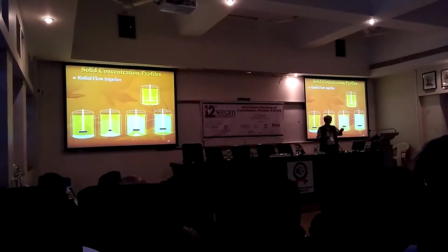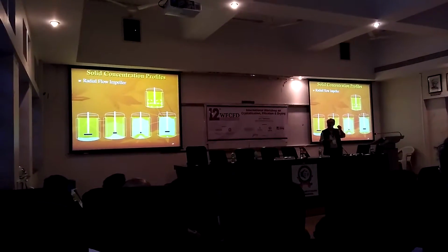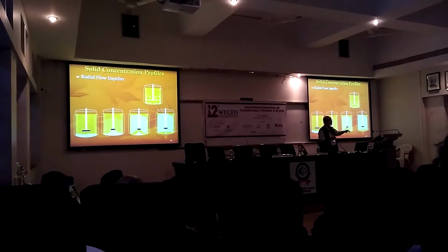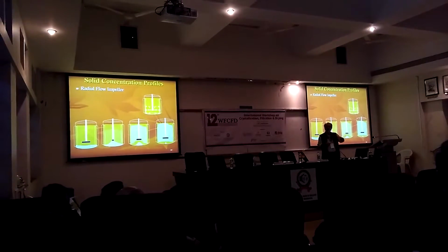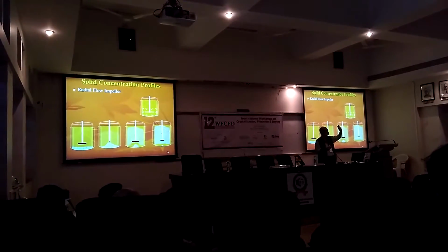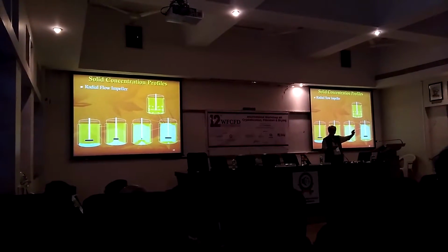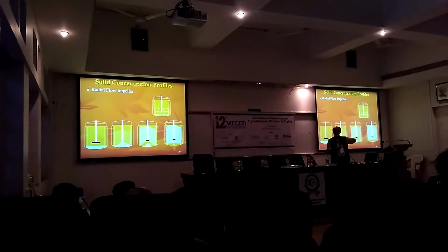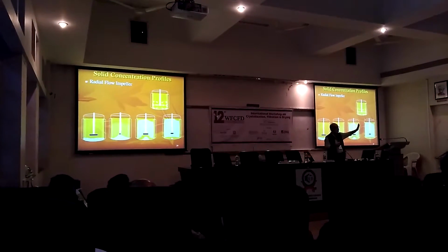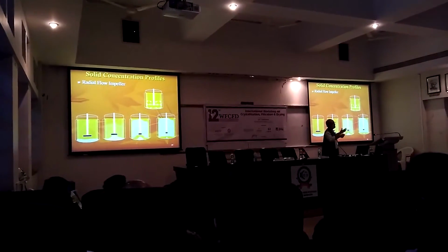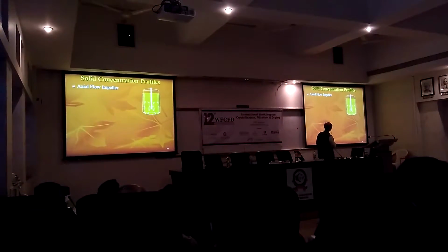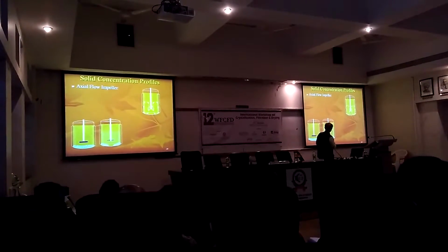However, if your objective is batch-wise and if your objective is to keep the solid particles in suspension, the amount of energy which is required for you to suspend and the amount of energy required to distribute it uniformly, there is a difference of 3 times. You need to supply 3 times additional energy when you want to distribute it uniformly as compared to just suspension. Just suspension is good enough when you want to have an exposure of the entire surface area for the particle growth uniformly. Exactly reverse situation occurs when you use an axial flow impeller.